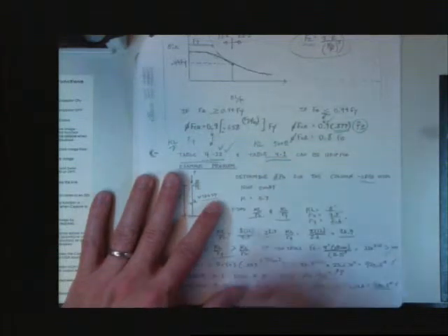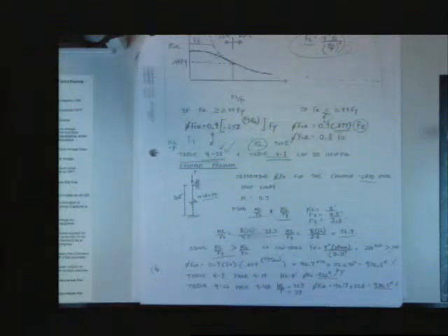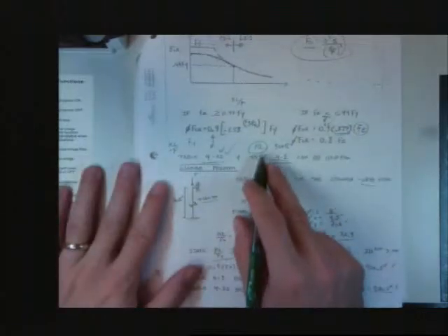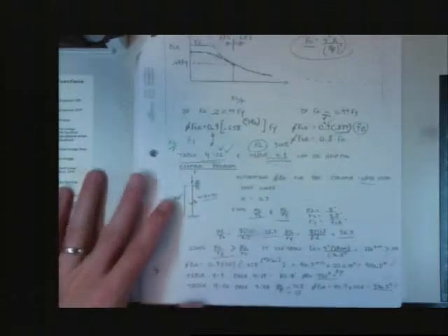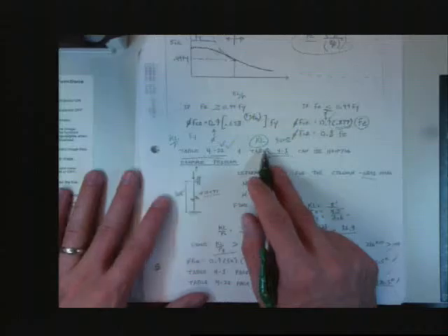But it's not quite that way. KL is derived with respect to the least radius of gyration. You're not dealing with the least radius of gyration. You have to trick this one, and I do that in a future problem. If you've seen that before, great. Review it. Make sure you know it. If you've never seen it before, read a book.